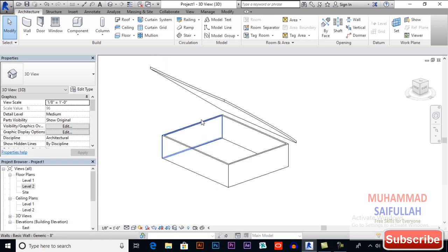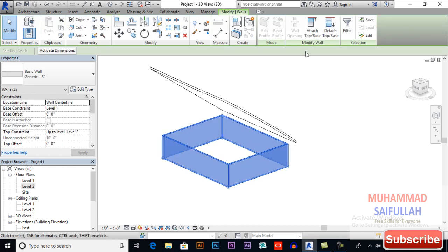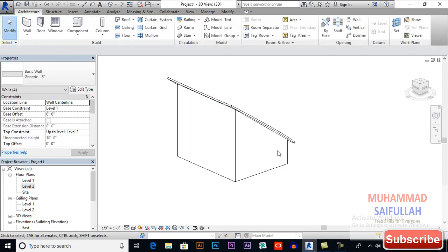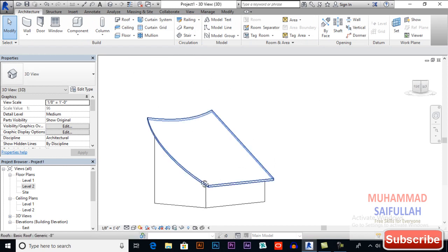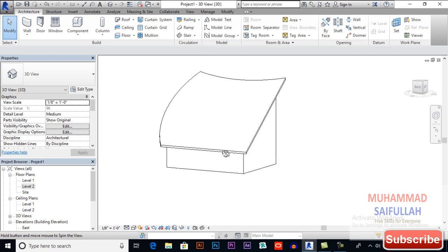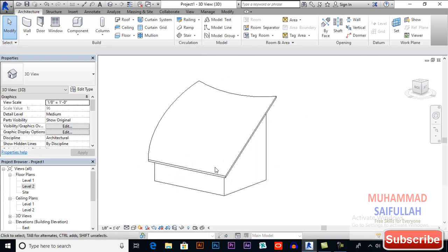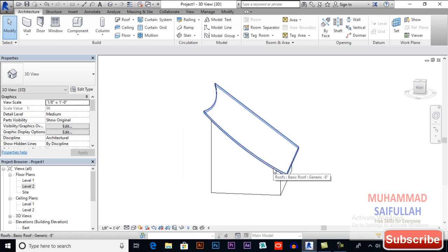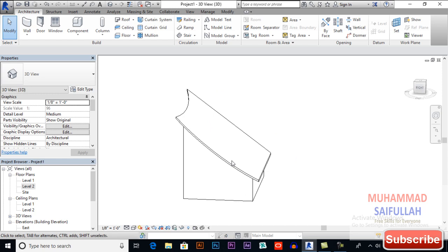I will extend walls to the roof. So hover your mouse over one of your walls and then press tab and then click on it and attach top base and select this roof. This is how it works. Try different options, so you will get better results and different shapes.